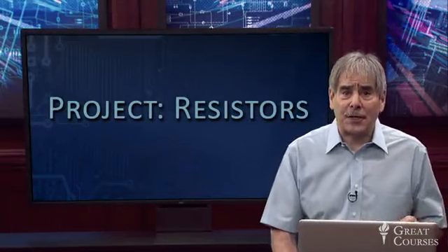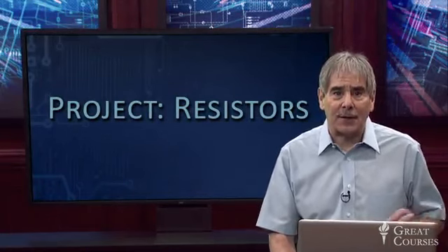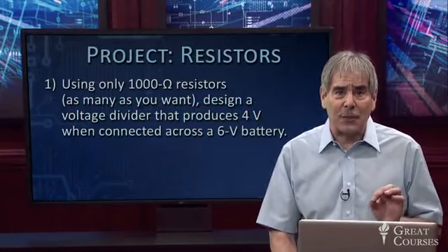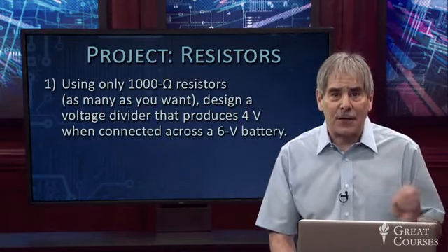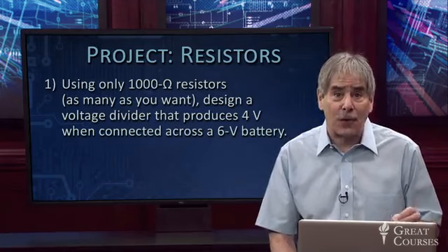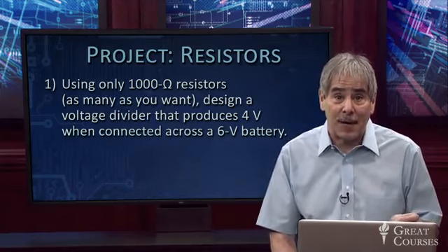So Lecture 2's project is a combination of design and calculate. I'm going to ask you to use only 1,000 ohm resistors, 1 kilo ohm resistors, as many as you want. Design a voltage divider that produces 4 volts when you connect it across a 6-volt battery.